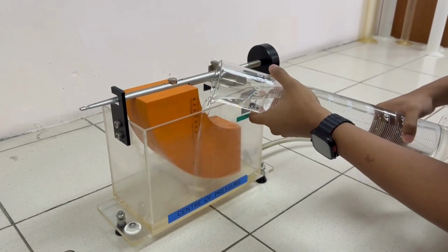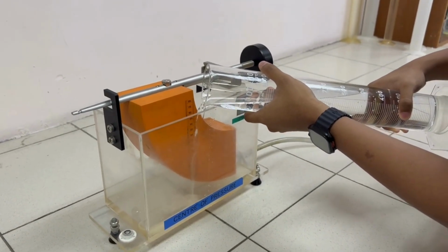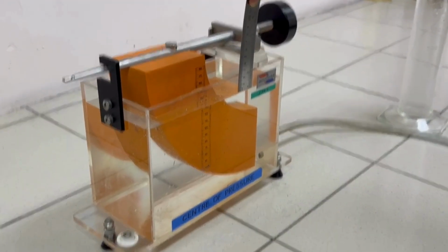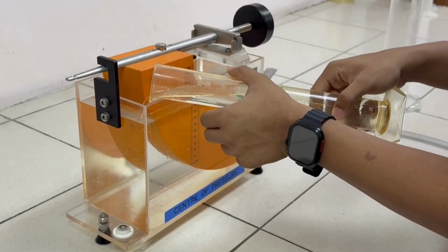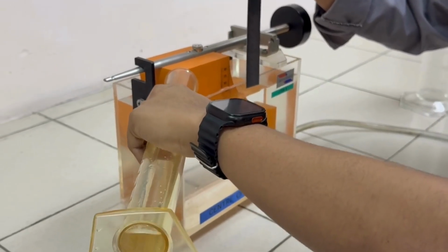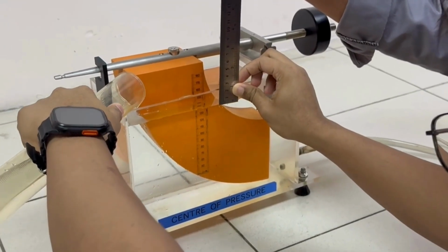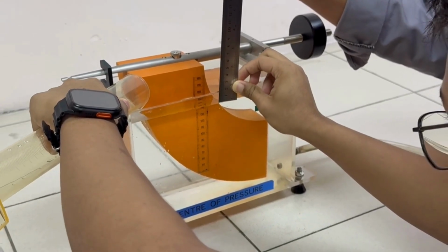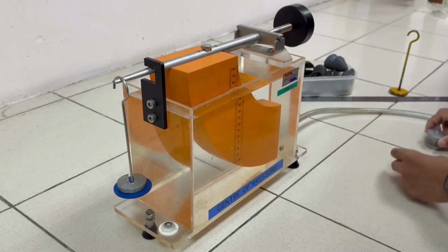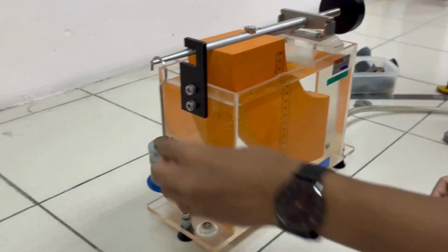Using the measuring cylinder or beaker, fill the tank with water to the zero scale datum, just touching the base of the vertical rectangular face of the toroid. This can be adjusted by opening or closing the outlet valve situated at the bottom of the tank. Fill the tank with water to a certain level about 1 cm from the top line of the tank. Place weights on the load hanger to restore the balance arm to the horizontal position.